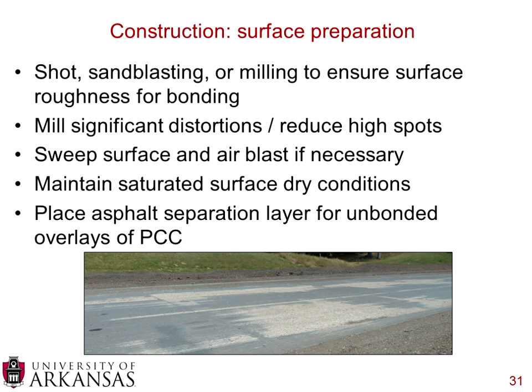After you've done any sort of sandblasting or surface roughening or milling to make your foundation for the new pavement, you do want to make sure that you sweep that surface. And if necessary, you can also air blast that, and that'll make sure to get rid of any sort of particles so you can get that good bonding.